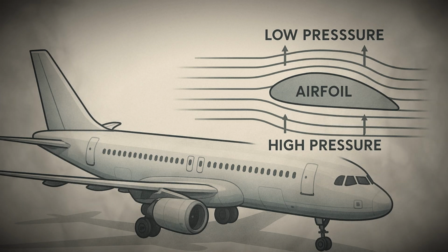The shape of the fuselage is typically streamlined to minimize drag, allowing the airplane to move smoothly through the air. For passenger aircraft, the fuselage must also meet strict safety requirements, with pressurized cabins to allow flight at high altitudes and reinforced structures to withstand changes in pressure. Cargo aircraft often have larger fuselages with wide openings for loading and unloading goods, while military aircraft may have narrower fuselages designed for speed and stealth.